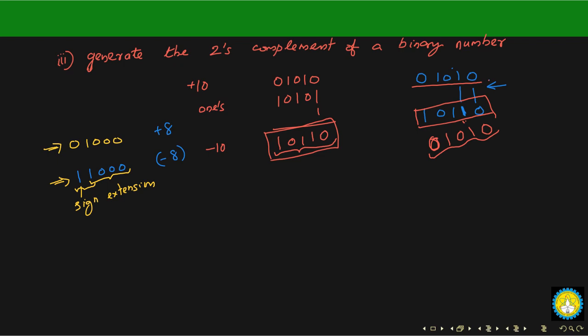Very importantly, you have to remember that you have to feed the input from this side to this side. That's how we are designing it. So even though your input is 0, 1, 0, 0, 0, you're going to feed it to the Mealy machine in a reverse way. That is, you're going to feed it like this: 0, 0, 0, 1, and 0, because our operation is like that. So that's very important. Remember that you're going to feed this in the reverse manner. Okay, so let's get started.